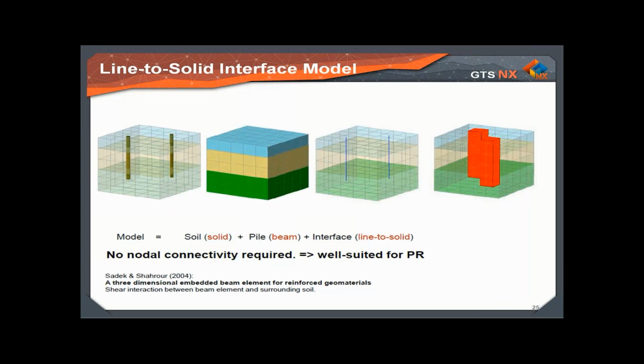Here I have to mention that the idea of embedded pile techniques goes back to the beginning of 2004. There was a publication by Sadek and Shahrour on a 3D embedded beam element for reinforced geomaterials. It was meant for reinforcement like anchors and things like that, and this was utilized here as a pile element. There was some modification, mainly the addition of the shaft interface, the tip interface, and the tip element, to become a pile element.